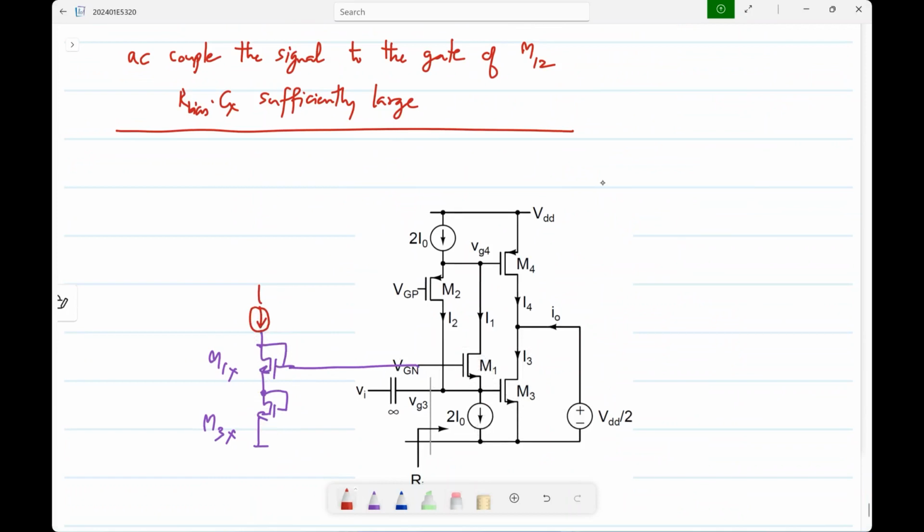Okay. The same goes on the upper side. In fact, I'll have the same bias current here and there. So here also between these two transistors and those two, it's a current mirror. Okay. So it is getting biased with a fixed bias current, which is what we want, right? We want a constant current bias in the transistors. But the signal voltage here and there will be the same, and it provides an infinite input resistance.